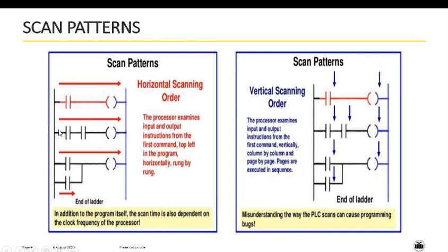This is from left to right, and again the control will come back to the second rung. The second rung will be executed, and the output of the second rung will be stored in the output memory. It will again come back to the left side, from left to right and top to bottom. In this zigzag way, the program of the PLC will be executed.